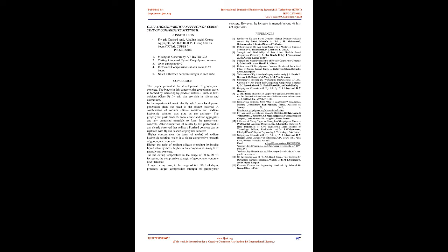Sodium hydroxide, sodium silicate solution. A combination of sodium silicate solution and sodium hydroxide, NaOH, solution can be used as the alkaline liquid. It is recommended that the alkaline liquid be prepared by mixing both of the solutions together at least 1 day prior to use. The sodium silicate solution is commercially available in various grades. A solution with a Na2O/SiO2 ratio by mass of approximately 2, say, Na2O equals 14.7%, SiO2 equals 29.4%, and water equals 55.9%, is recommended. Sodium hydroxide with 98% purity, in flake or pellet form, is commercially available.